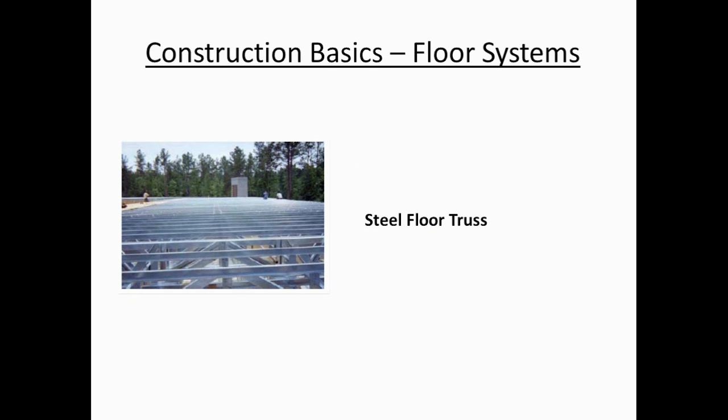Another option for floor systems is to go to a floor steel truss. Again, we have a very lightweight structure that can be used for long span applications, greatly impacted by panelization, and really can work into your production schedule. Really accommodates MEP runs. The downside is, again, it chews up a little bit of elevation.